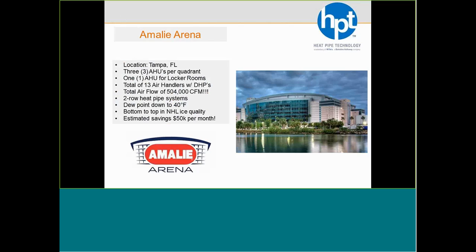So they designed this very expensive desiccant system to really dry out the air. It involved this expensive system on the roof, gas going up to it, all kinds of good stuff. Problem was it shot their budget, and they couldn't afford it. So they tried to figure out how they can get a system they can afford and still get this dew point down. So the answer was just using basic chill water air handlers with wraparound heat pipes.